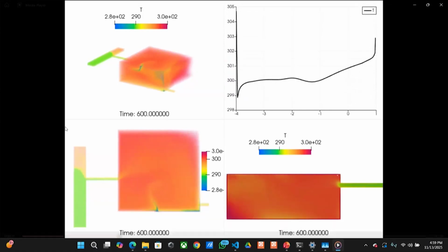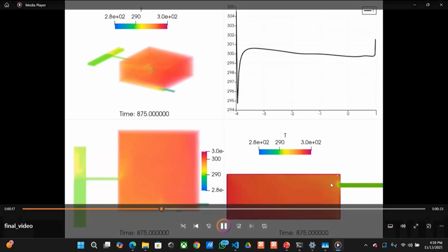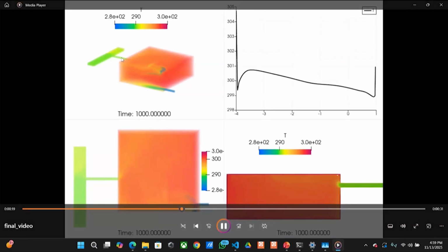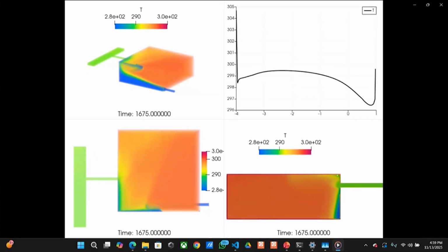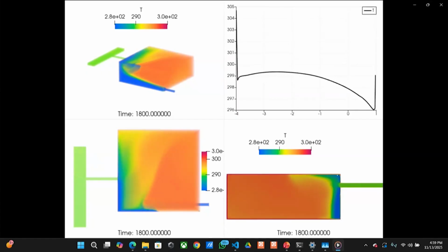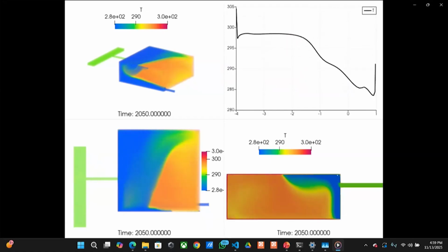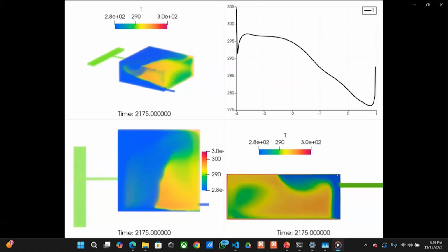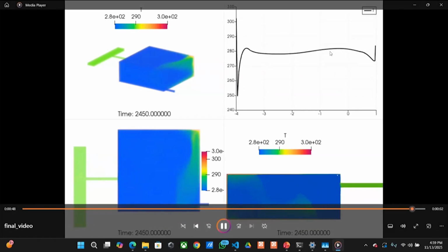And I wanted to see how the flow regimes are working. I took a clip in this direction so that I could see how the cooling is happening in the particular region. This is the top 2D view, where you can see how it is getting cooled from the top. And this is the temperature value. I have plotted data over time. It is a time-consuming filter, but it will work eventually. And once the room is getting cool, the simulation is also reaching the steady state.